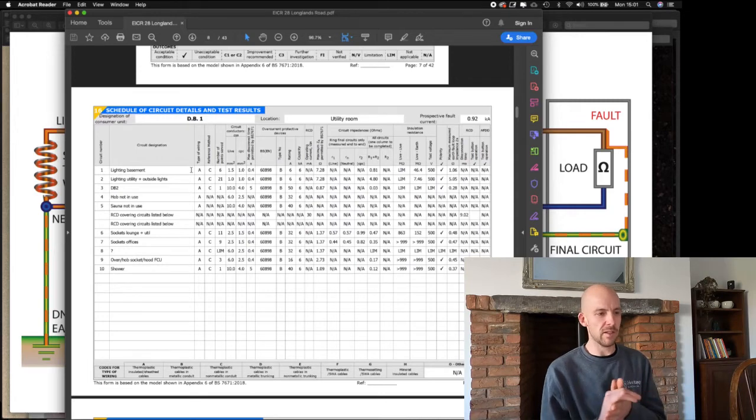Just to give you an idea, we note down the size of the conductors. As I've said already, the size of the conductor dictates how much current that cable can carry. So with lights, they are not very current hungry pieces of equipment, especially with LED lighting, which is prevalent these days as opposed to, say, old halogen lamps. The cable's therefore much skinnier, and it's fine being skinnier.